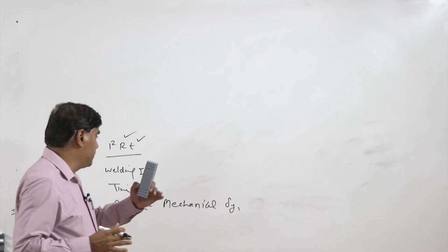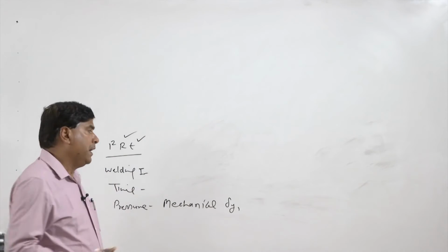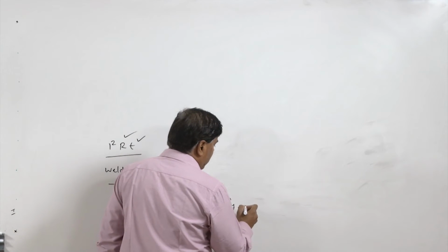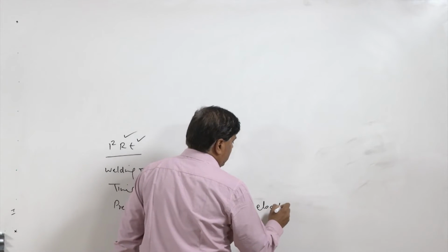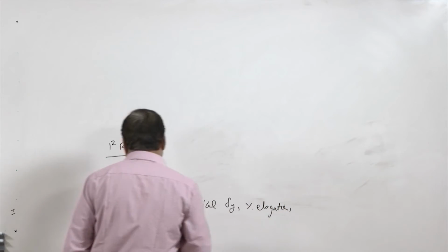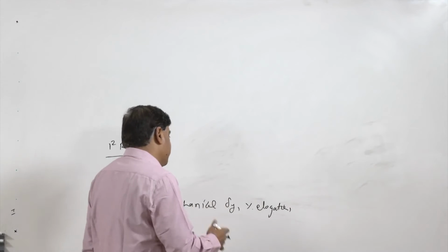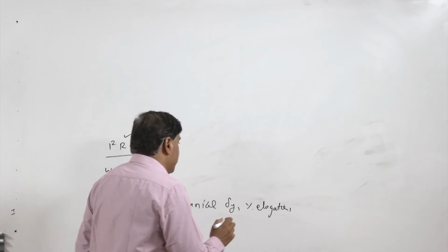High yield strength materials require a greater application of load in order to achieve the metallic intimacy which is needed, and the percentage elongation. High ductility materials will require lesser load or pressure as compared to low ductility materials.